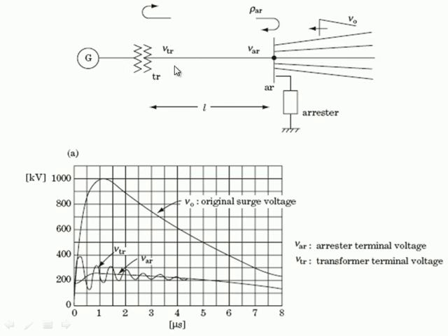However, if there is a change in here, suppose there is a short circuit or any surge, before affecting the generator windings, they have to deal with the transformer winding. As transformer windings already have a high value of inductance, that will protect this generator. This inductance will oppose those transients and it will protect the generator, which is very costly.